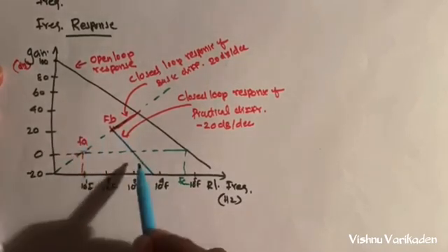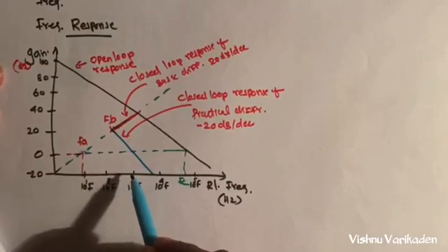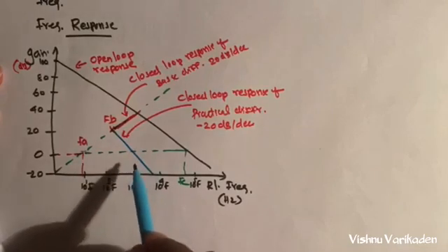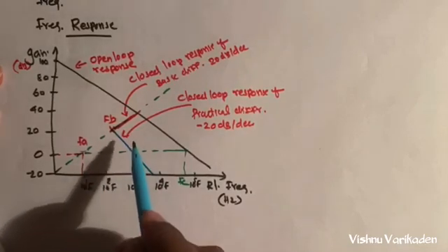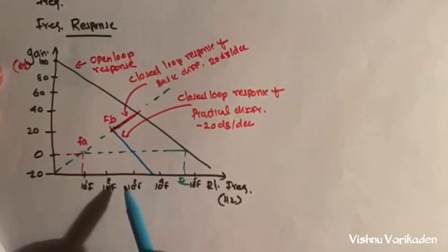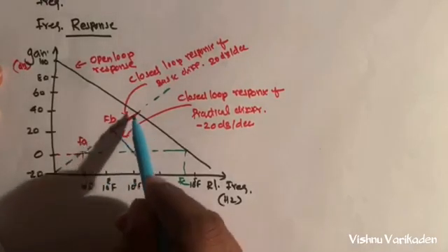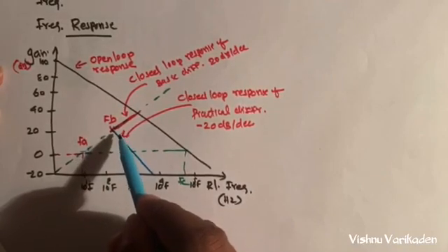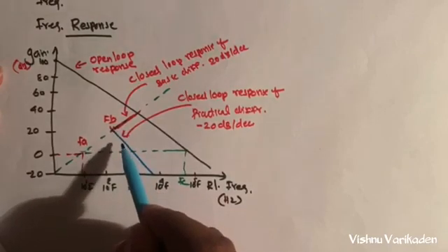That is shown in the plot. So this 40 dB per decade variation in gain is due to the R1C1 and RFCF factor. In an ideal differentiator, the frequency response would steadily increase at 20 dB per decade even beyond FB, which could cause stability problems at high frequency.